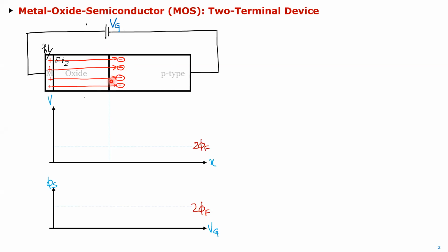So if I look through the voltage, I have these two bars here. Let me first draw this one. So apply some VG, let's say. As this is oxide, this voltage is going to linearly vary till this point, and that potential we call the surface potential over here. Okay, and then from here it goes in that parabolic fashion, just like in the PN junction.